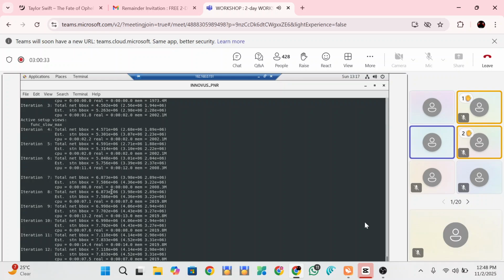Excuse me, sir, I have a question about the power plan. Are the power plan calculations done by the physical design engineer or are other engineers involved in this? Okay, that's the question. Basically, power estimation will be done first by the power team. Once the power is estimated, accordingly they will give the power numbers for your power plan: how much grid is required for each and every metal layer. Then that value should be used in the physical design.